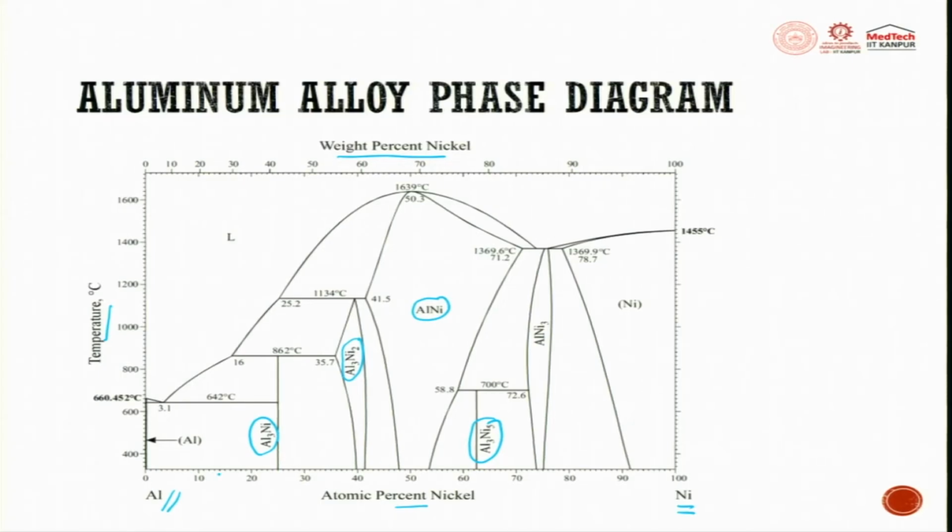Depending upon the composition you have mixed in powder bed fusion or in directed energy deposition, you mix that alloy in the starting material itself, and when we expose it to laser, it undergoes various temperatures. Depending upon the temperatures, various phases get formed.